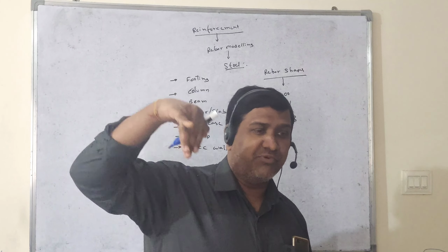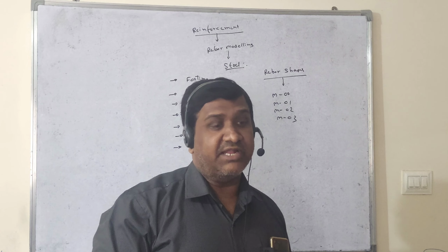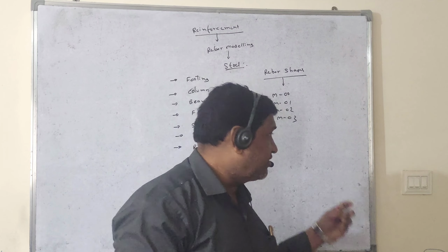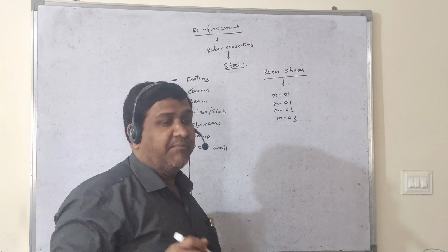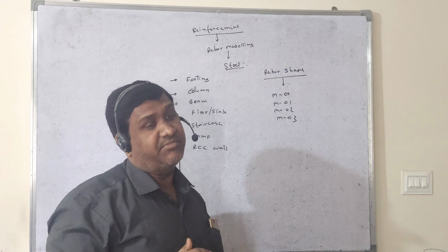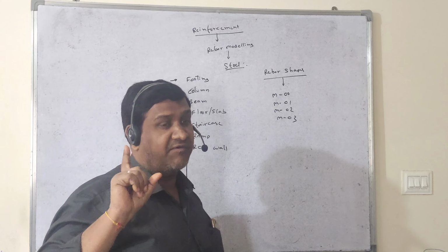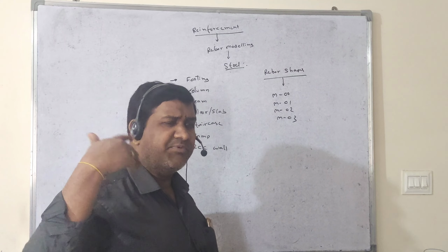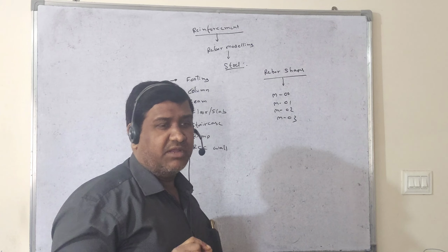For the lapping, we have to put some bend, a 45 bend or 90 bend, whatever shapes we require, and we have to do it here. All these shapes we call rebar shapes. In BIM, all these shape families will be there. Each and every shape has one family, so there are multiple families. You just go and choose the shape, and it will become that.